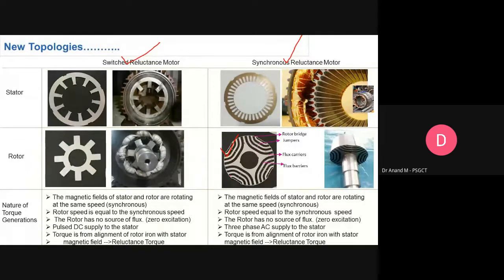Maybe in future we can think about PM assisted type of rotor configurations, by increasing the saliency ratio of the rotor and using appropriate FOC control of the drive system. Maybe this can be compatible when compared to the different magnet grades, as we know that magnets are very volatile with respect to cost, and we depend on imports, and there are also manufacturing issues with respect to the machinability of the magnets and inserting the magnets into the machine. Maybe in the long perspective, the synchronous reluctance motor may be a viable choice for the vehicle electromagnetic drive.